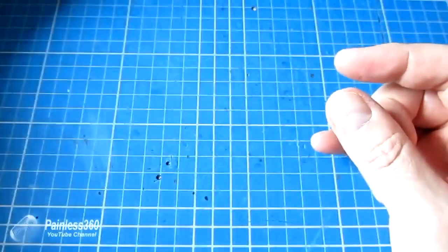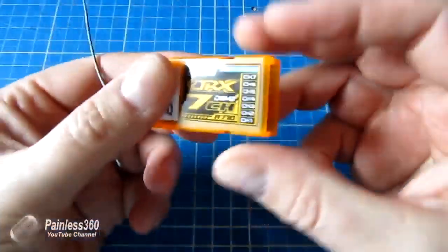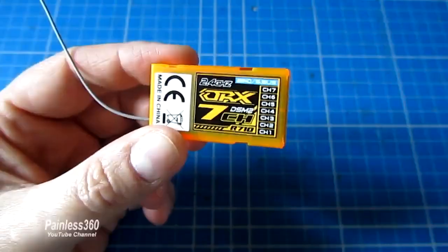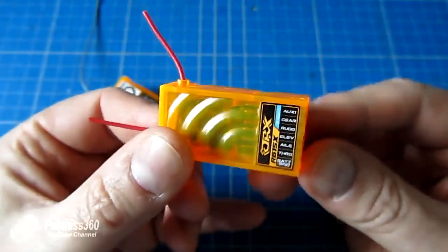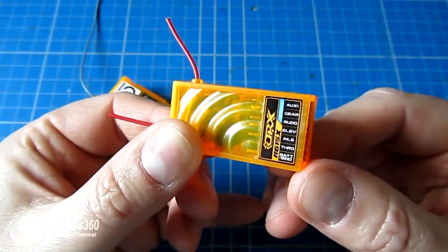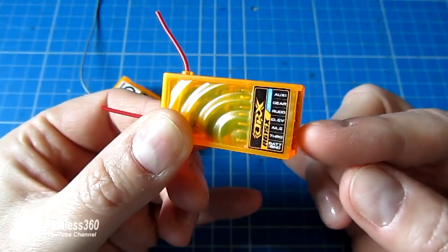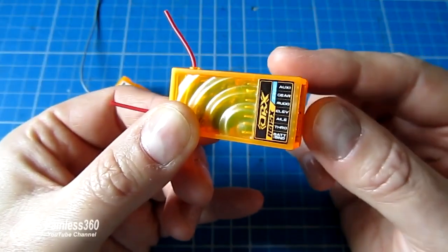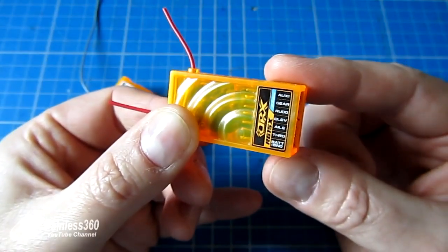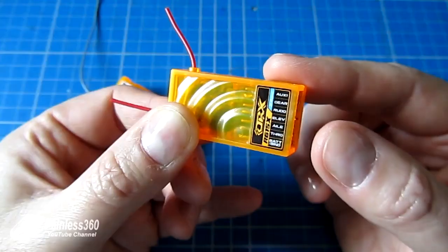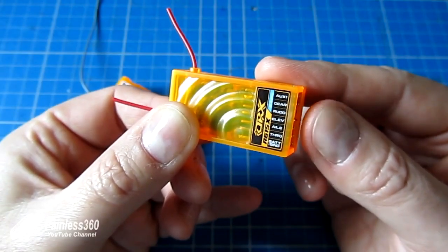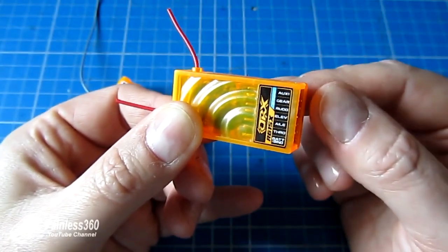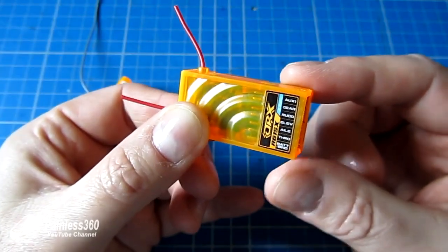If you actually look on the individual receivers themselves, this one's actually slightly easier. This is a 6-channel. You have the battery bind at the bottom, and then it goes throttle, aileron, elevator, rudder, gear, and then auxiliary 1. And each of those channels correspond to one of the controls that we were just looking at. The throttle, aileron, elevator, and rudder are on the sticks. The gear and auxiliary 1s are typically separate switches.